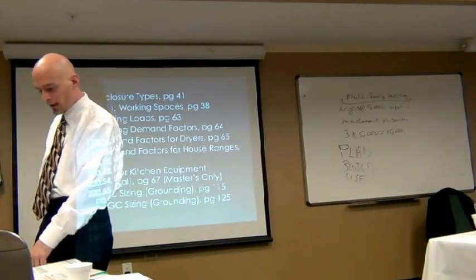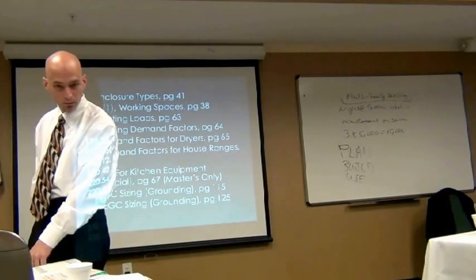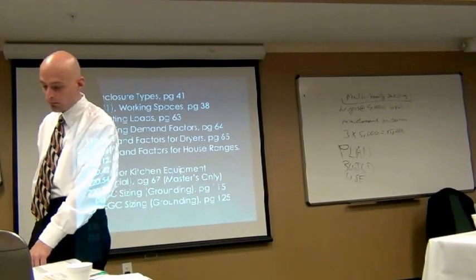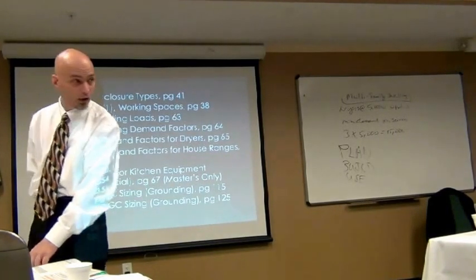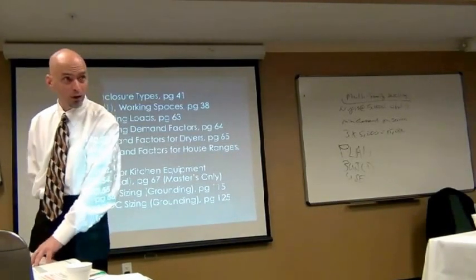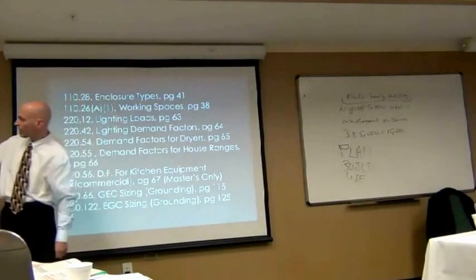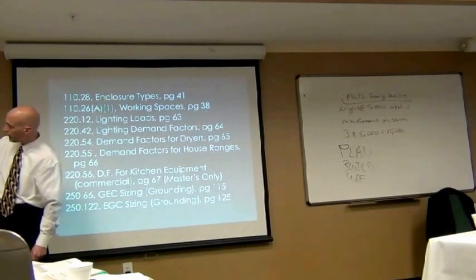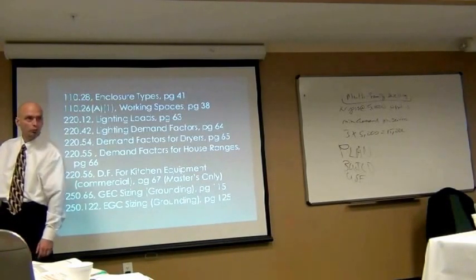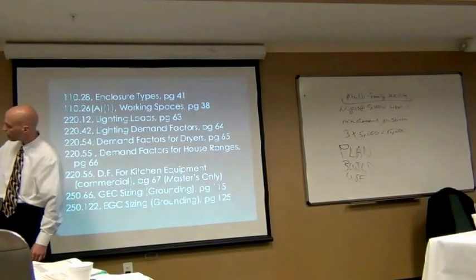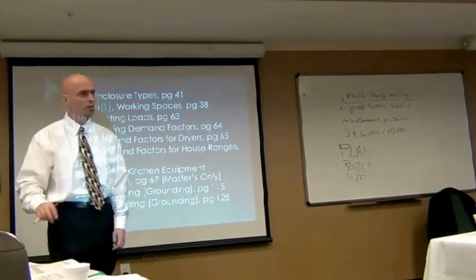2-aught or 3-aught would have a minimum size of what aluminum? Number 2, right? Is what I said was aluminum, not copper. I said copper up here, but what I said for the GC was aluminum. Be careful of that. So it would be a number 2 aluminum or number 4 copper if you're pulling the same conductor material. Everybody see what I'm talking about?